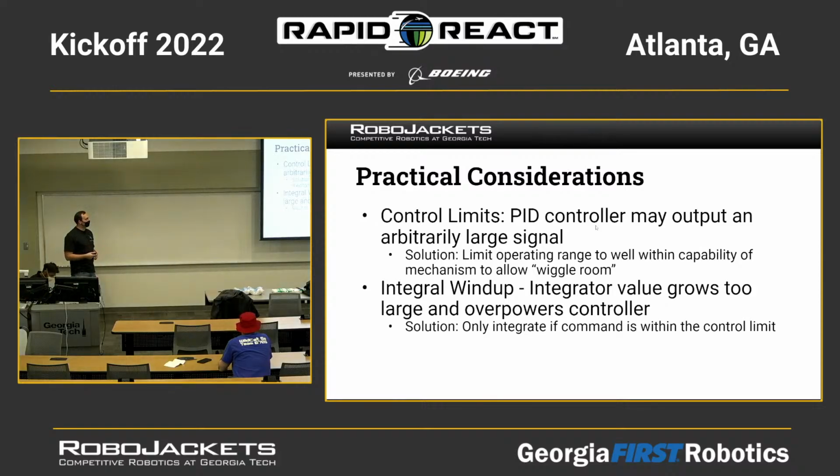As I talked about a little bit, so like practical considerations, right? The thing you were saying, I don't cap any of the accelerations, or essentially cap the torque of the motor, so it becomes physically impossible pretty quickly. So you'll want to do that, and it'll give you a little bit different behavior. But most of the same rules of thumb apply. And then also I talked about integral windup. So one thing you can do is just cap the integral value.